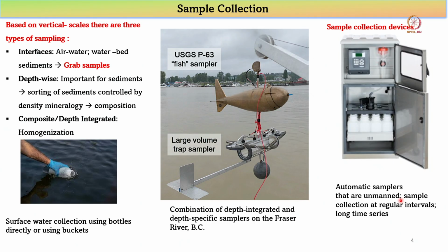Now this becomes more prominent in deeper lakes, and where there is a lot of organic matter in those lakes, where the bottom sediments are, a lot of redox related processes can be happening, which is giving the dissolved data a look very different from what is at the surface water. So when you have that kind of a system, it is extremely preferable that you take samples from different depths.